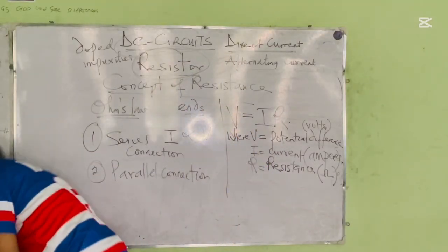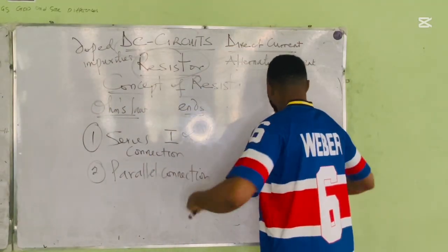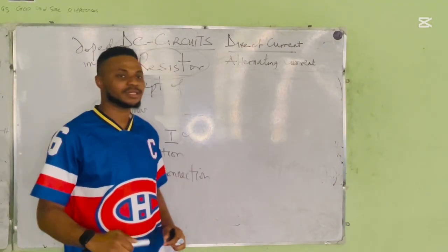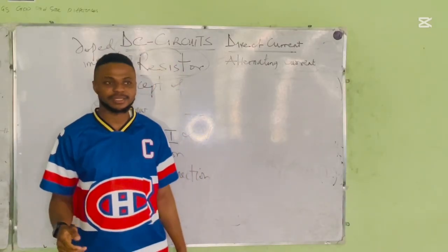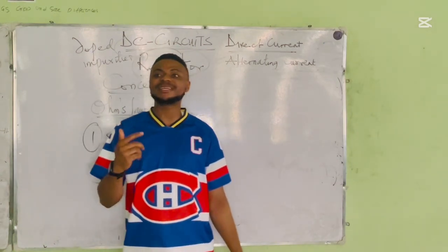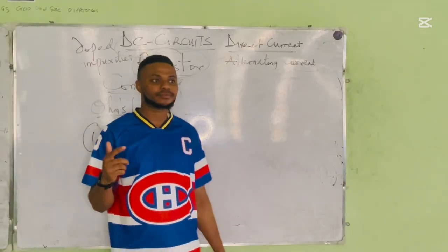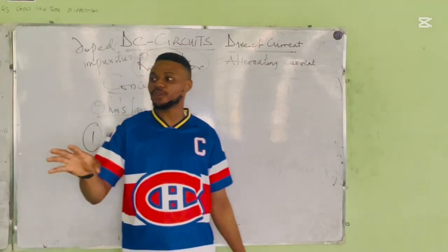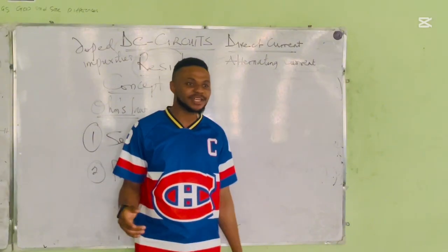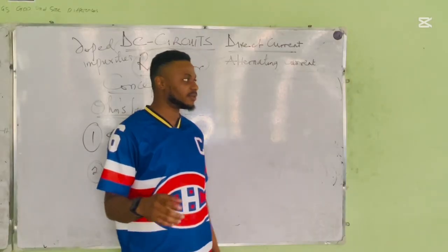So now, for series connection, take down: resistors connected in series have the same amount of current flowing through them, but different voltages.